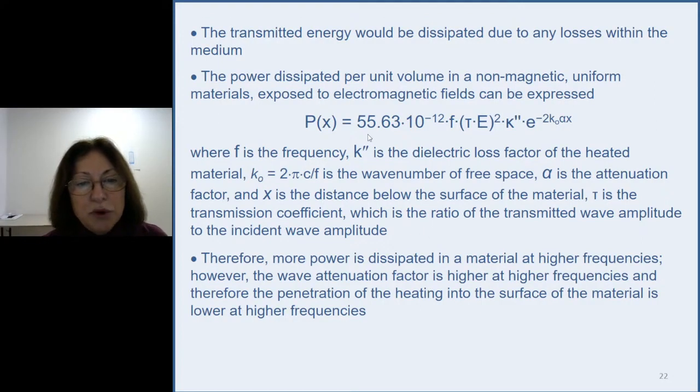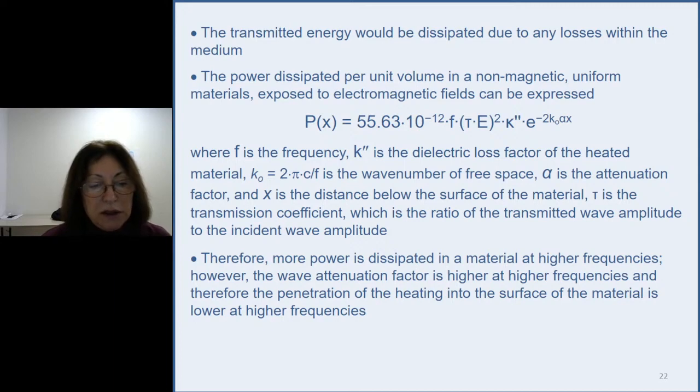It is very important to recognize that this power dissipated per unit volume depends on the frequency, and so consequently the dissipation rises with the frequency. So more power is dissipated in material at higher frequencies. However, the wave attenuation factor is higher at higher frequencies, and therefore the penetration of the heating into the surface of material is lower at higher frequencies.